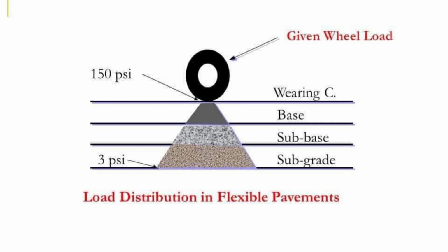This increase in the contact area is an indicator for us that the asphalt wearing course will face more load and is more critical as compared to the others. That is why it also has more bearing capacity as compared to the base layer and sub base layer, due to which it can successfully face the point load. And finally, the second layer facing more load is the base layer, and then the sub base.